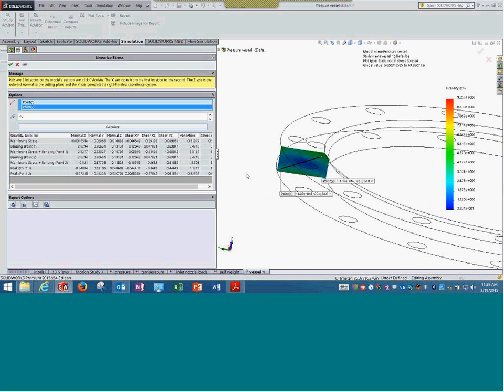The other specialized codes directly get this using FEA and can compare it with the ASME code inside the software to see whether it is acceptable or not. So we reach only this stage where we are plotting this, and one has to take these results and do further detailed analysis and comparison with the ASME results.